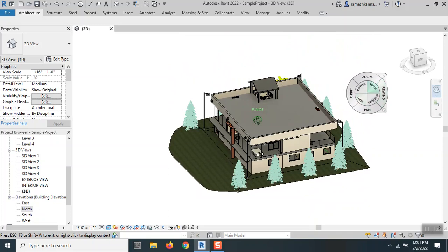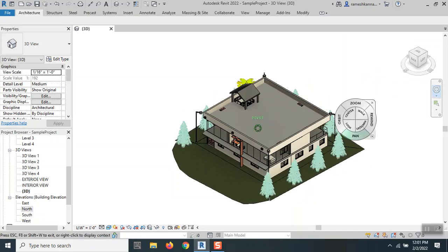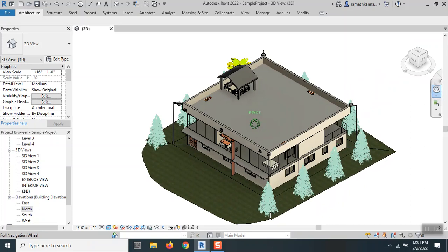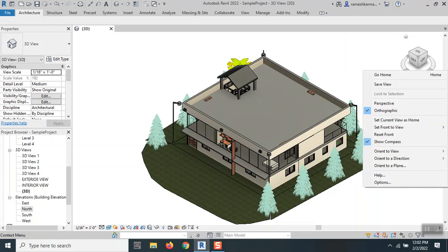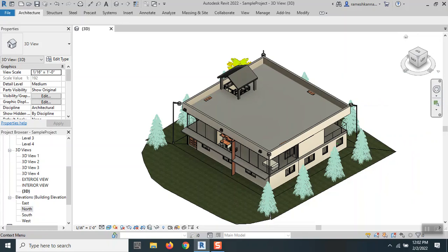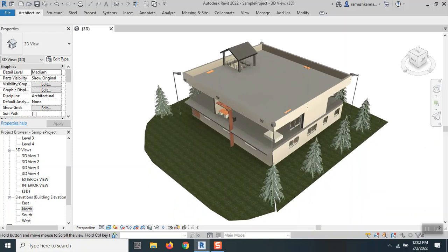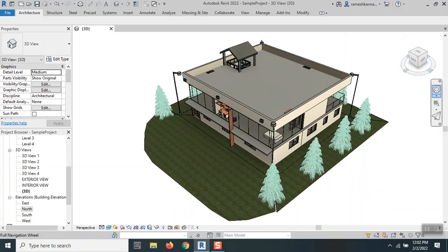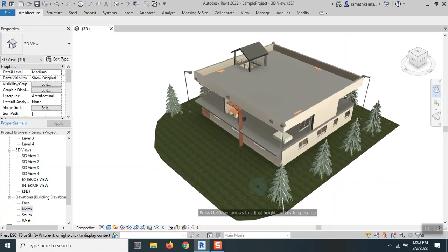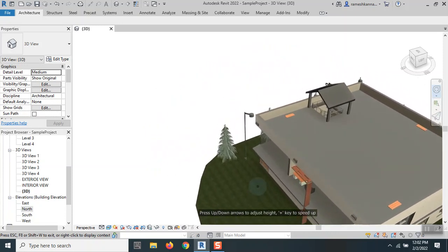Right, so the walk needs a perspective view. So first I'm gonna go to the original view of it. Then I'll dock here. When I click dock, it will go into that navigation bar, and I'll give the context menu, and I'll change it to perspective. The entire model is now in the perspective view. Right, so I'll just move that a little bit. Now I'll go back to this, and I'll check this walk. So I'll click walk. So you see, this is how I just walk, kind of thing.